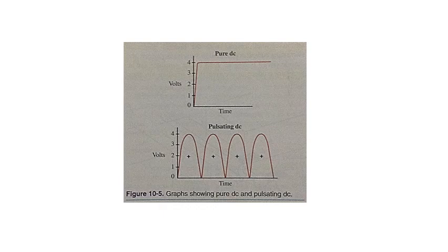The rotating armature is connected to the outside circuit through commutators or slip rings. The commutators and slip rings touch brushes in the outside circuit. Generator brushes are constructed mainly of simple soft carbon.